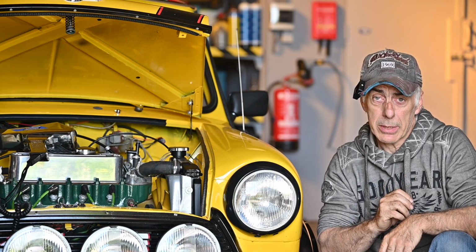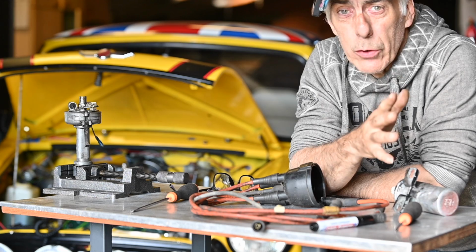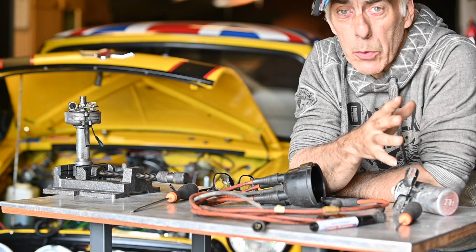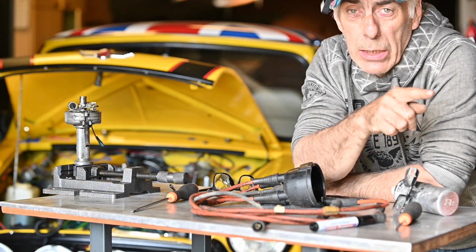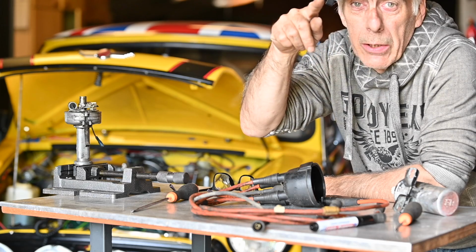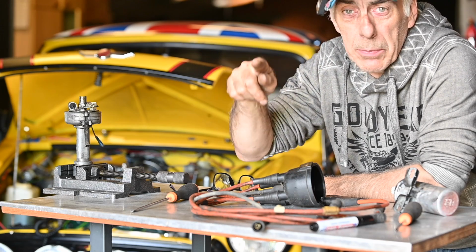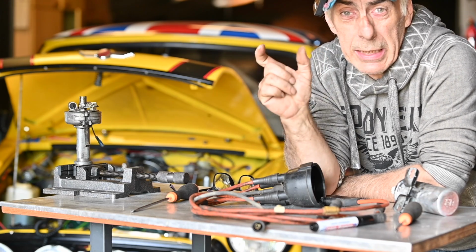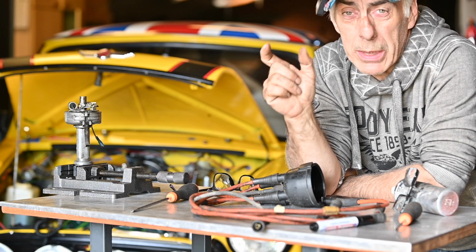However, there is a small problem. The problem is that the air-fuel mixture does not explode immediately. It needs a little bit of run-in time, then it hits its peak, and then it's going to come down again. And it's exactly that peak that we want to have at the right moment in time.